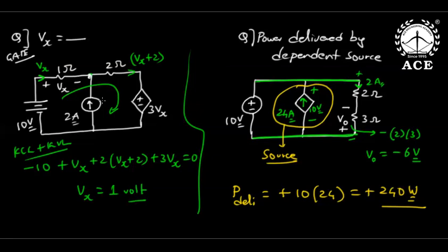It all depends. Suppose you do nodal analysis. The best way to remove confusion is to take this as the reference node and find the node voltage here. If this node voltage is less than 10 volts, then this current is already decided by this voltage source only. Actually, we cannot declare anything because there are multiple source networks. If there are only passive elements, then your argument is straightforward, because current will definitely divide. But here, because active elements are also there, it depends.